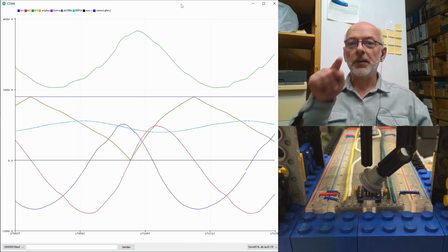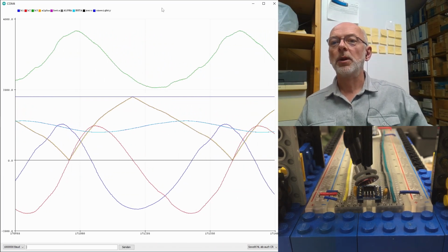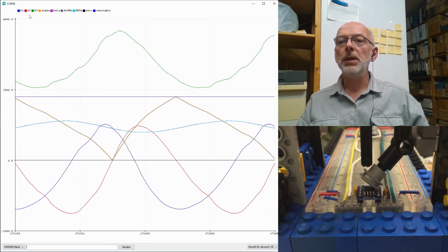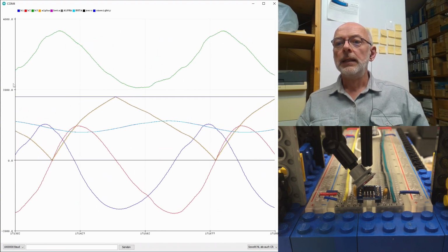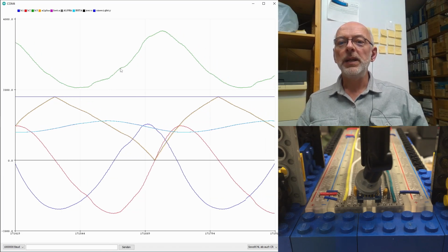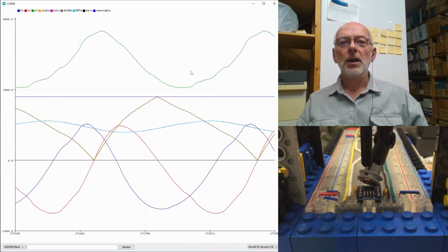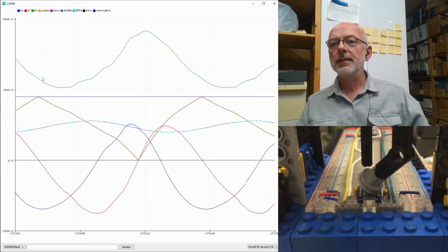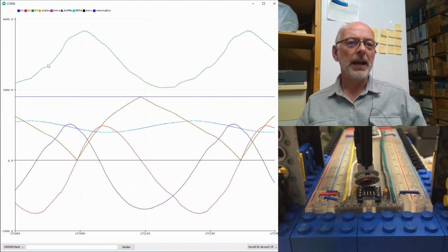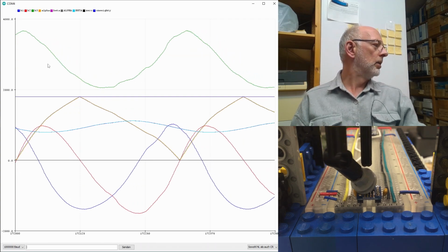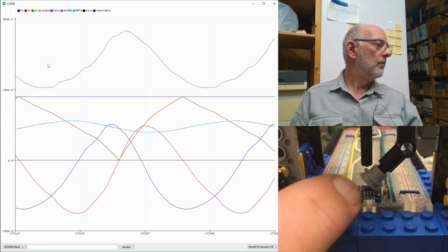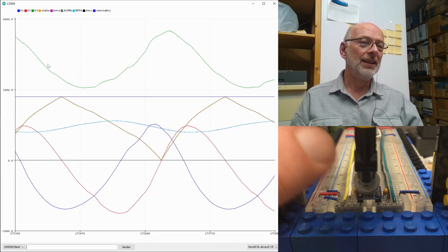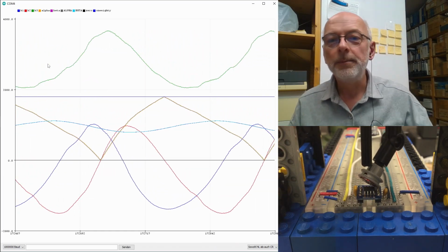And as always, the look onto the serial plotter. So we have here blue, red and green, our B1, B2 and B3 signal. Please note our B3 signal has a quite large amplitude here and is always in the positive range, which is understandable because, yeah, our magnet always points down with its north from the top.